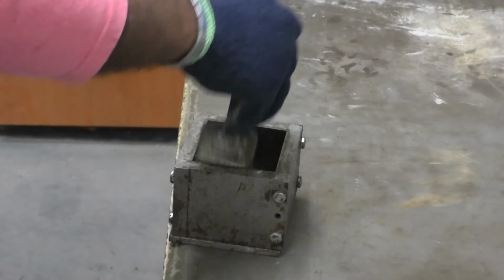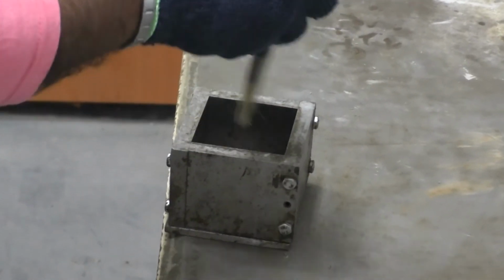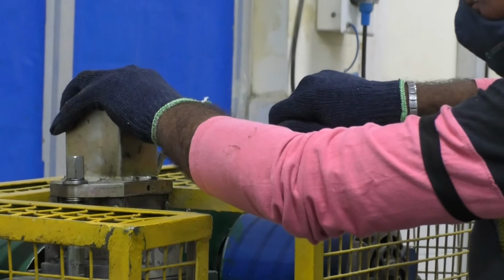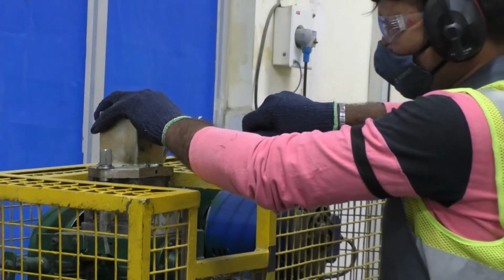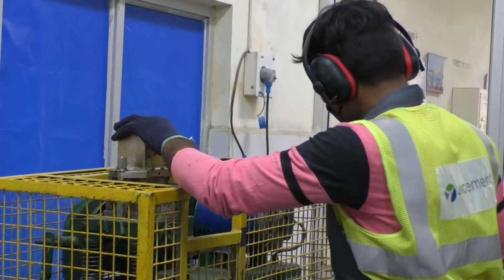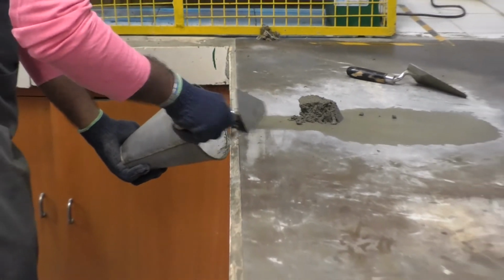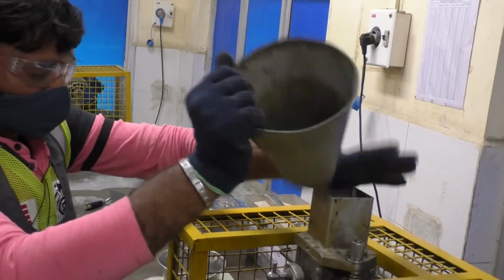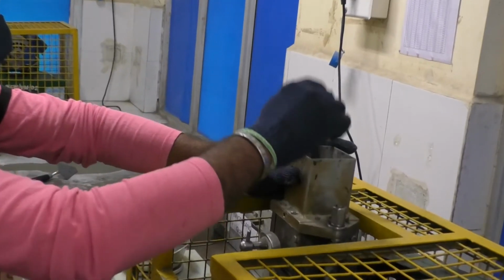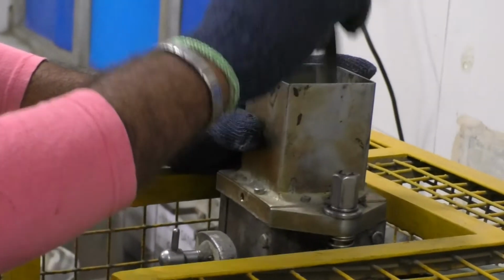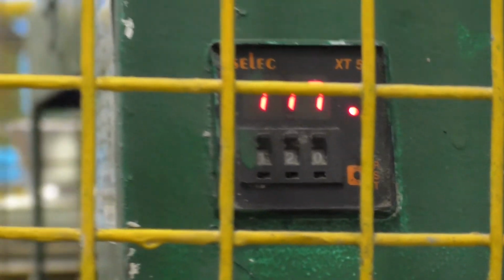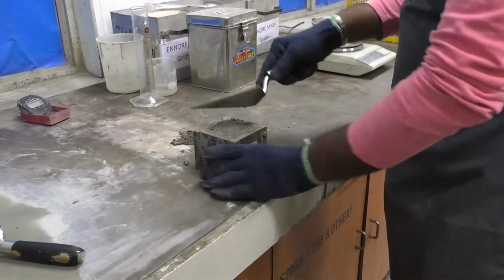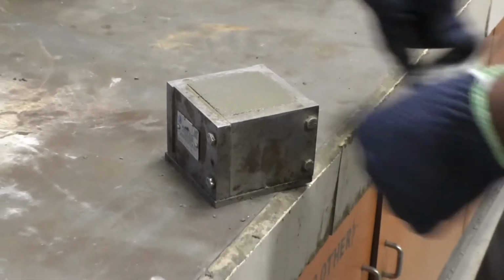Simultaneously, keep the mold ready by applying oil on the inner side of the mold. Then fix this mold on the vibrating machine by tightening the nuts. Then add the cement sand mixture with the scoop and fill it in the mold on the vibrating machine in 2 layers, and press the mixture with a poking rod. Remove the mold from the vibrating machine after 2 minutes and smooth the surface of the mold with the trowel.